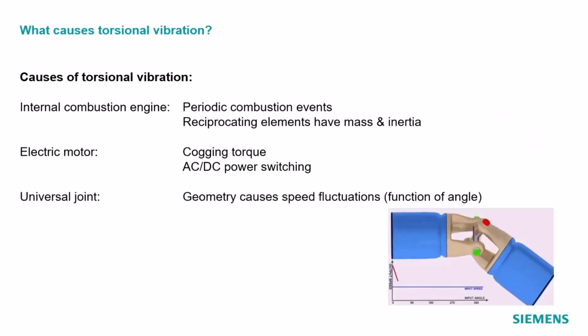So there's a balance there trying to make it run smooth. And then you've got things like this universal joint. You can imagine it's twisting around, allowing things to run at an angle. This also will create speeding up and slowing down, like that might be twice per rev in this case. Does that make sense to you, Charles? Yeah.